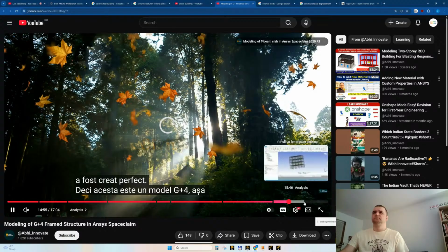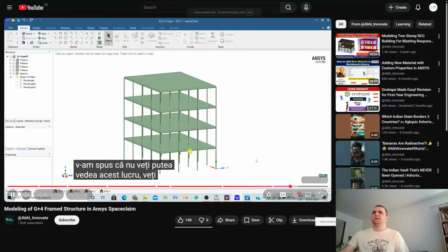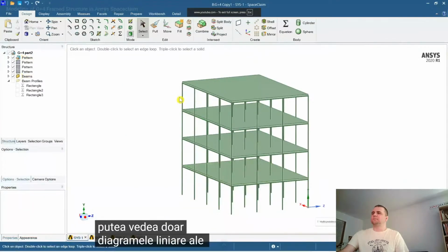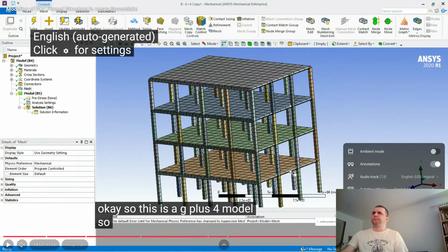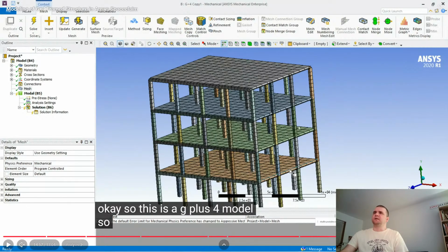Yeah, it uses line bodies because we see this. Look here, we see line bodies for the columns. And also in the mesh, we see this interference. Some patches, these are from the line bodies. A problem here is that he didn't unite the lines. There is an option in SpaceClaim to unite the vertices and the lines. So this column should be one column, yes, not separated.